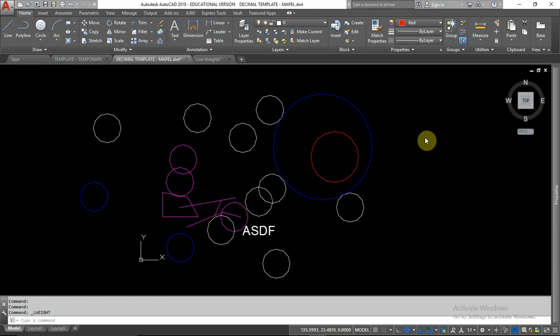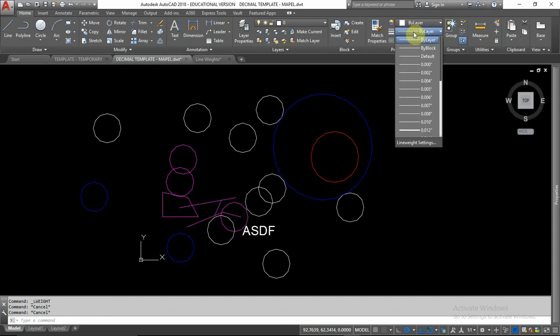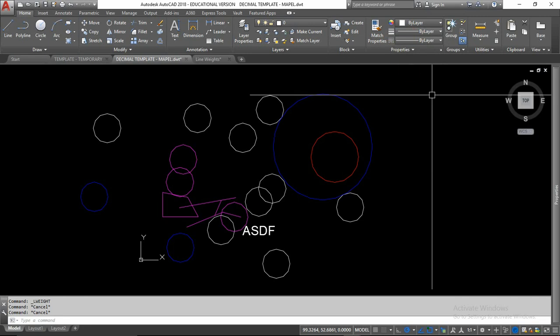Okay, we're still on the properties panel of the home ribbon. We've discussed colors. Let me go ahead and change this one back to by layer for creating new. We've discussed line weights, the relative thickness or width of the lines. Again, polylines have a width characteristic or setting. I recommend talking about relative thickness for your lines or for line weights.